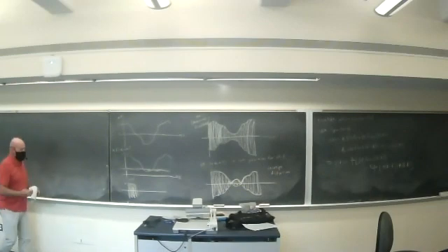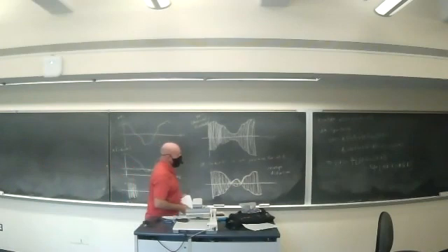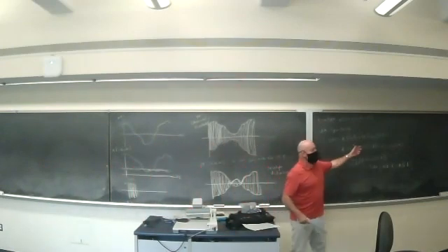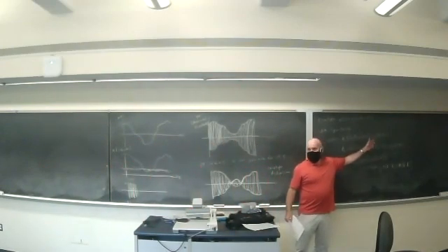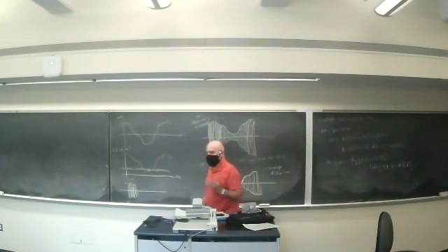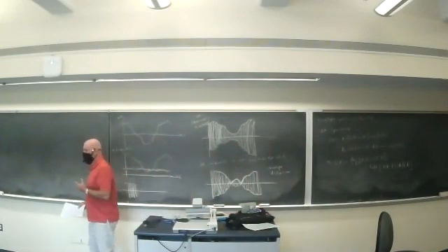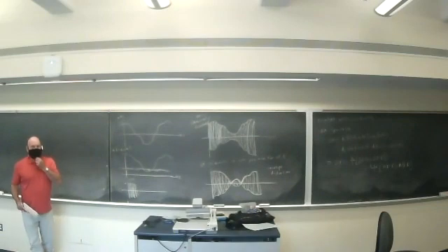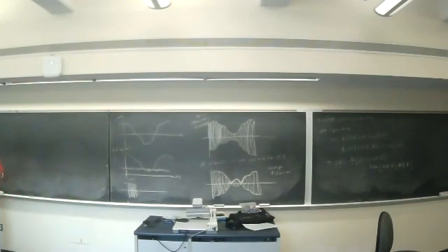And really mathematically, this thing to generate this S of t is quite simple, right? I need a function generator that creates a high frequency sinusoid and multiplies that times my message, and I've got AM radio. Okay. Now, hardware multipliers aren't necessarily easy things to build. There are a lot of different circuits that you probably haven't seen in electronics to build them, these modulator circuits, but they're relatively simple. You know, a few diodes.